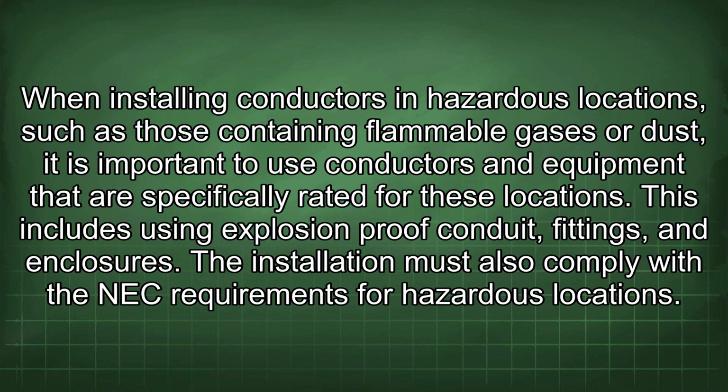When installing conductors in hazardous locations such as those containing flammable gases or dust, it is important to use conductors and equipment that are specifically rated for these locations. This includes using explosion-proof conduit fittings and enclosures. The installation must also comply with the NEC requirements for hazardous locations.